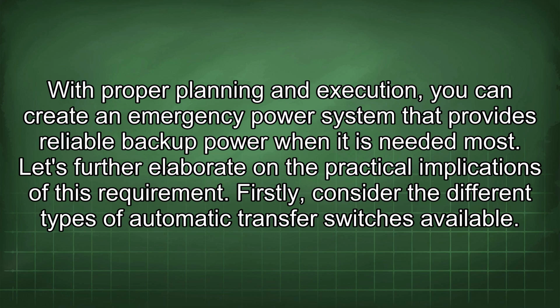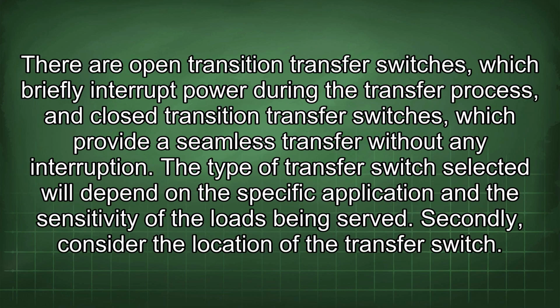Firstly, consider the different types of automatic transfer switches available. There are open transition transfer switches, which briefly interrupt power during the transfer process, and closed transition transfer switches, which provide a seamless transfer without any interruption. The type of transfer switch selected will depend on the specific application and the sensitivity of the loads being served.